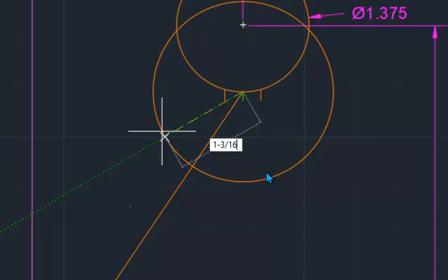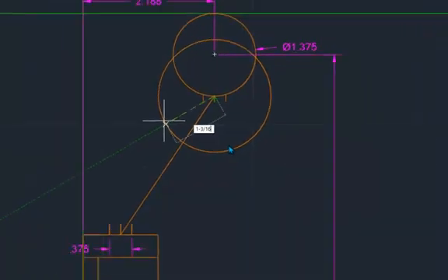And by the way, you can make this into a decimal drawing. Just make sure that you use the right precision. That doesn't mean set the precision for 3 decimals and let everything go. Not everything's going to be 3 decimal places. And also, do not suppress the trailing zeros. Inch drawings need to have those zeros so that we can figure out what tolerance it has, because there's a big difference between 8 and 8.0 and 8.00. I know sometimes they get in the way, and you can't have too many. So you have to look at what your tolerances are. How many decimal places do you need to have?